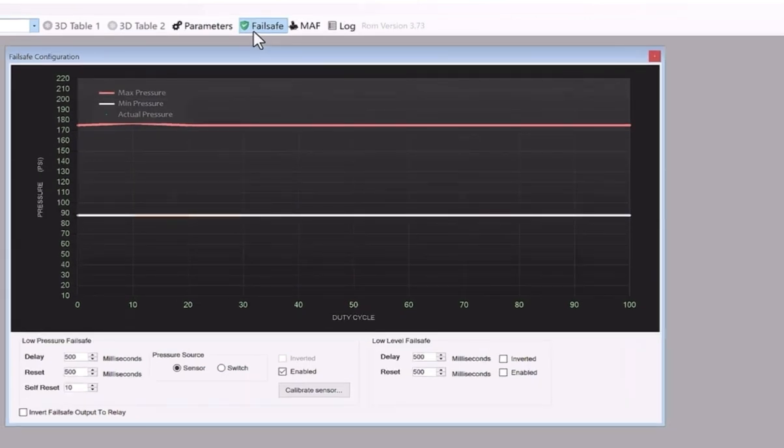The pump simply keeps the line pressurized while the fast pulsing solenoid determines how much flow is provided to the engine. With Frostbyte, you can have confidence in its robust failsafe system that ensures protection in the face of malfunctions, whether it's a blockage or fluid loss. The failsafe mechanism is designed to take immediate action by interrupting the main engine control unit, ECU, reducing boost, lowering the rev limiter, and transitioning the car into a safer, less aggressive tune to safeguard the engine.